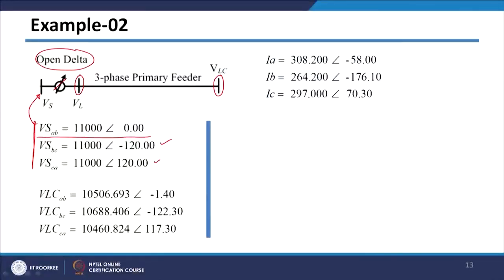However, here we are having a 3 phase system. So in case of 3 phase, to calculate the settings of your regulator, we need to do load flow studies first without the regulator. So without the regulator, calculate the voltages at this feeder end by keeping these voltages Vs at this end.